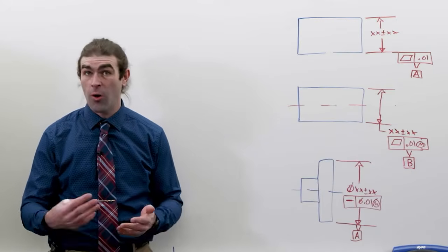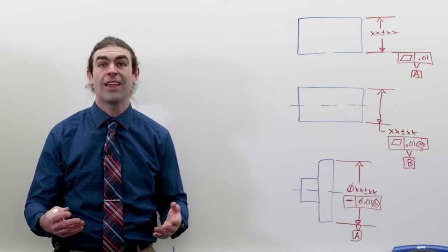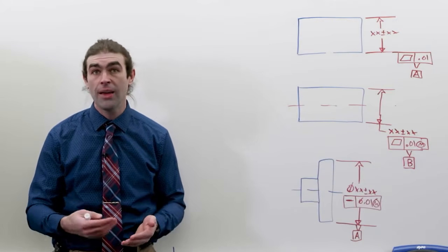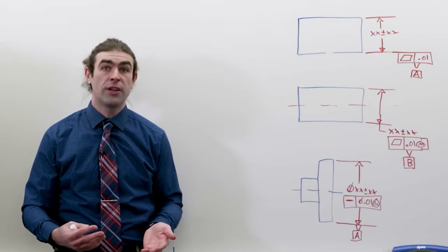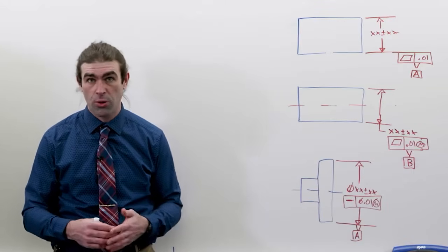I personally like the old way a little bit more because it made drawings slightly quicker to read. If you saw a datum feature symbol on a feature control frame, you already knew it was a feature of size without having to do any more looking.